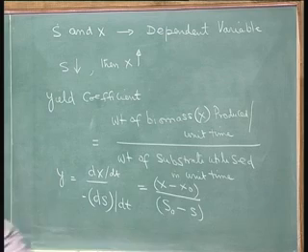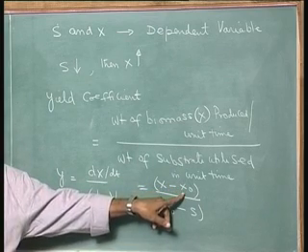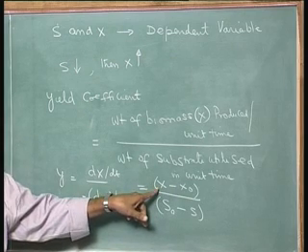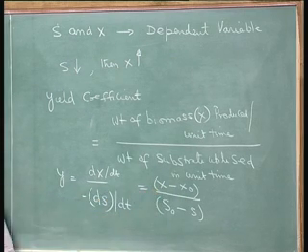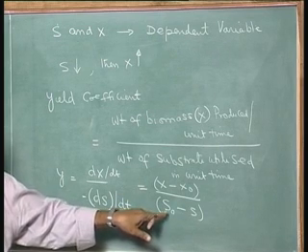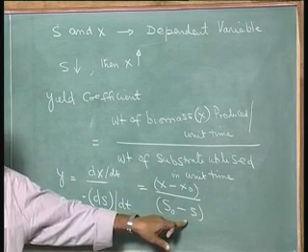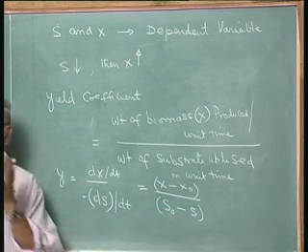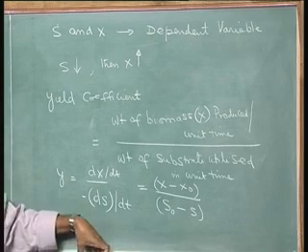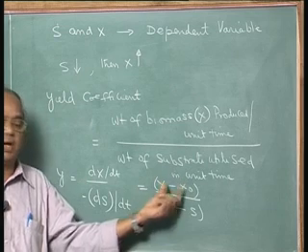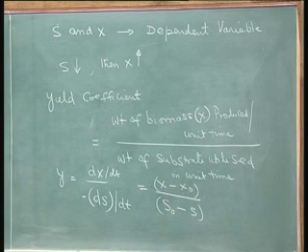In this, X naught is the concentration of microorganisms at time t equal to 0, X is the concentration of microorganisms at any time. Similarly, S naught is the concentration of substrate at time t equal to 0, and S is the concentration of substrate at any given time. So this S naught minus S is the substrate that is being utilized by the microorganisms. When they utilize the substrate, this much amount of biomass is produced. So this is the equation we have.